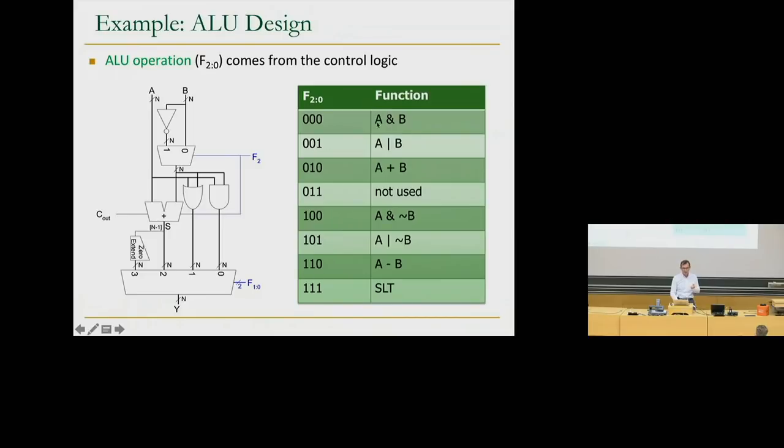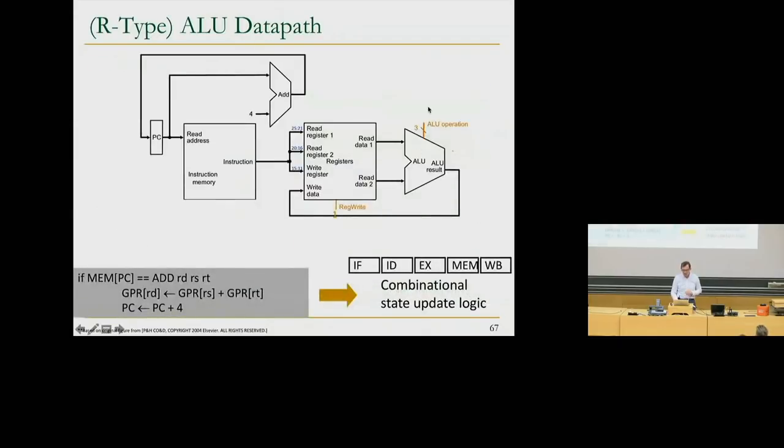If you're doing a bitwise AND, it's different. If you're doing an add, the ALU operation is this. And you might be doing other stuff also, depending on what your ISA specifies, right? So basically, this is the control signal for the ALU. And depending on the instruction opcode, or at the bottom, that funct part, remember the function part in MIPS, you set the ALU's control signals accordingly.